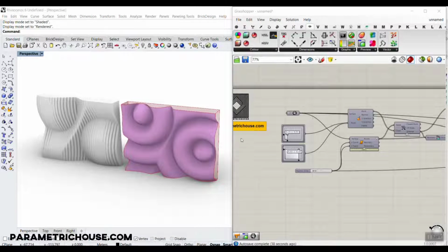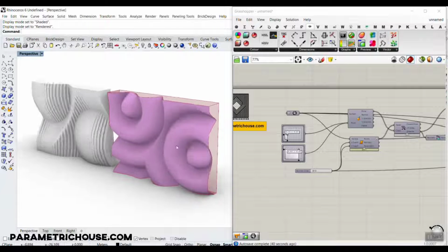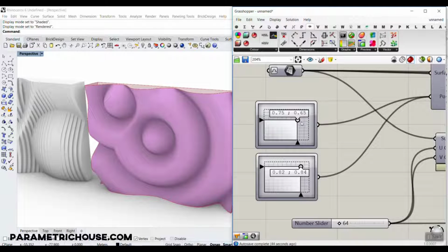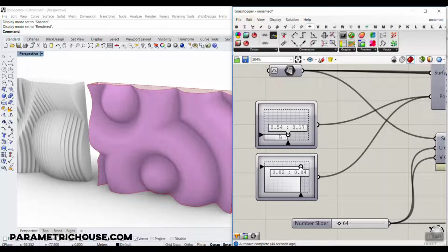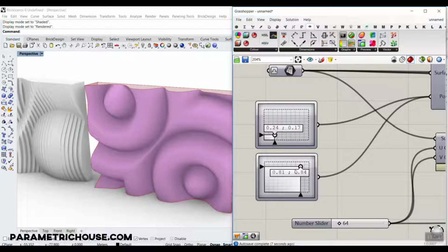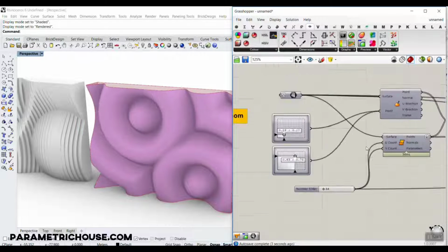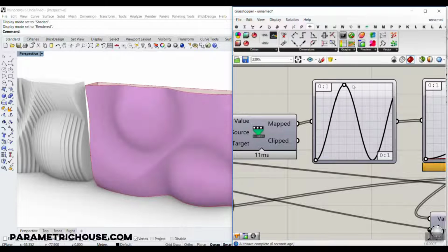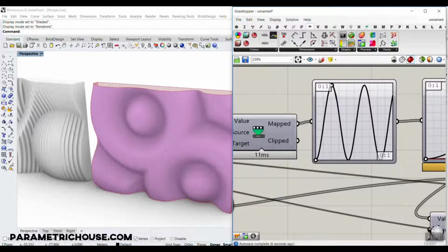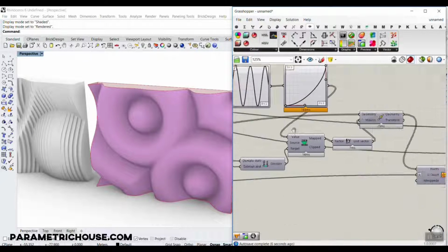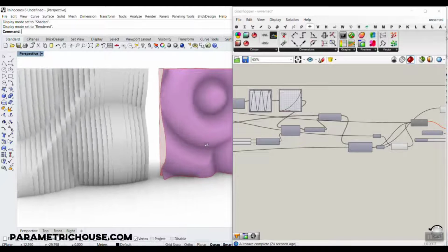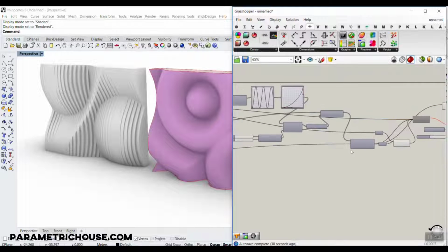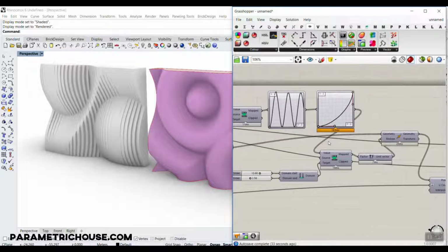In this Grasshopper tutorial, we want to make a parametric wall. As you can see here, I can change the location of the point attractors, and I'm going to explain how to use point attractors to make the parametric wall, and how you can change the distribution from linear into nonlinear with graph mappers, which we will use in this tutorial to change the form of the surface. And finally, at the end of this tutorial, we'll produce a series of extrusions which will make the parametric wall in Grasshopper. So be sure to watch the video till the end, and let's get started.